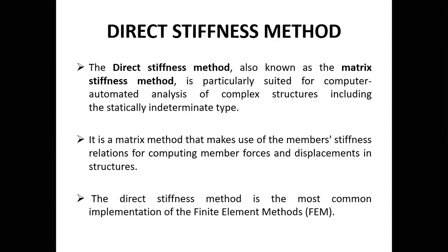It is totally based on computer programming, like finite element analysis. The basis is the stiffness matrix method, where we develop the displacement coordinates for different cases and form a matrix for it, and the same can be analyzed using computer programs such as STAAD. This also makes a member stiffness relationship for computing member forces and displacements.